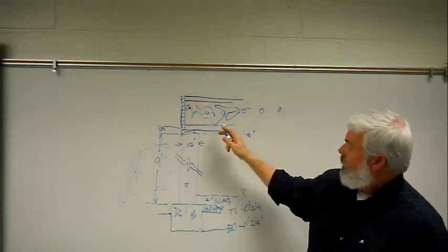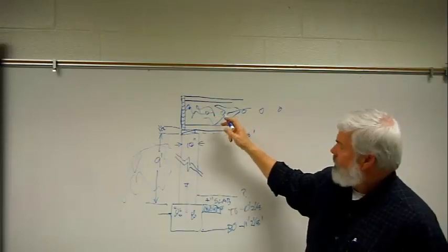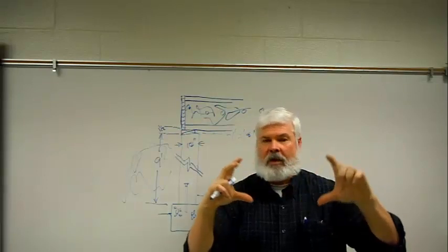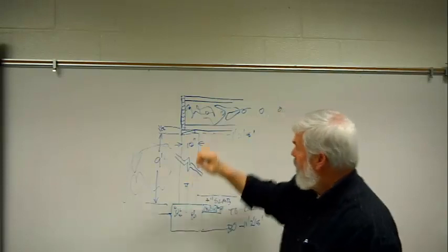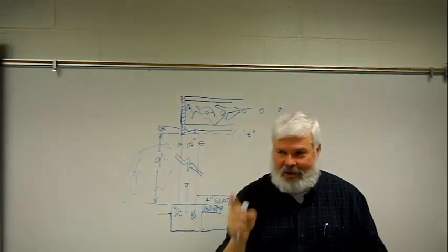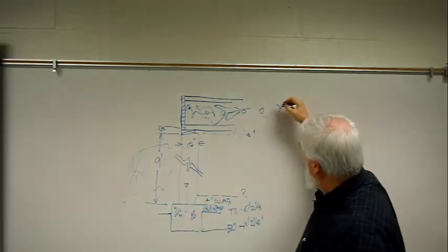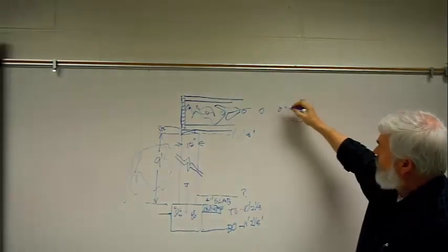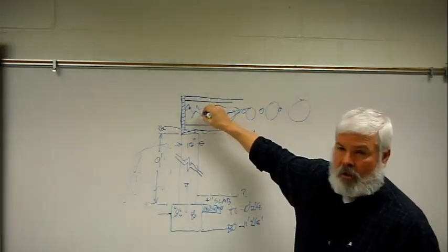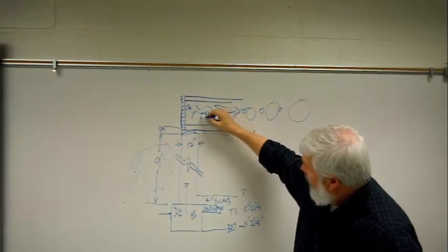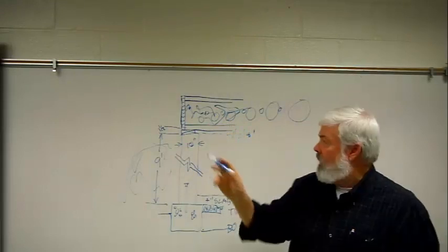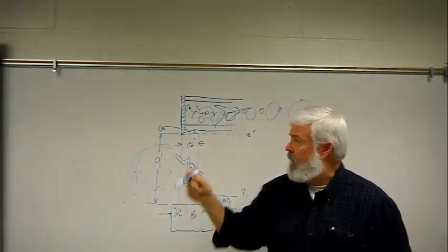But where would you think we could put the largest hole, like a hole we wanted to cut that was big enough to put a piece of 6-inch pipe through? Would it be near the wall, or would it be near the center of the span? Near the wall. That seems logical. But it's in the center of the span, all the way over here, where you can put the larger hole. And as you get closer and closer to the wall, the size hole you're allowed to cut out of this center part of the I-joist gets smaller and smaller because of the way the product holds the loads. The top member and the bottom member are in tension.